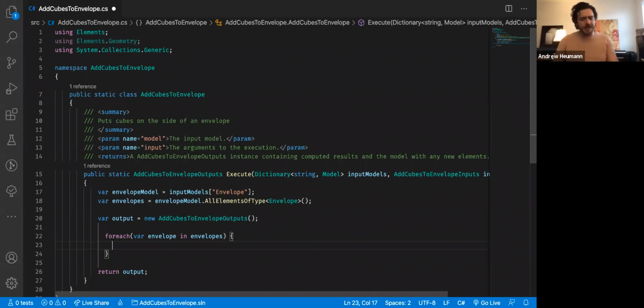Because one of the things that's different about elements versus, like, Rhino Common is that typically we're not working so much with solids and B-reps. We produce them, obviously, but you're going to have better results if you work with the generating geometry, like the 2D generating stuff that produced it. I wouldn't go get the faces of this.